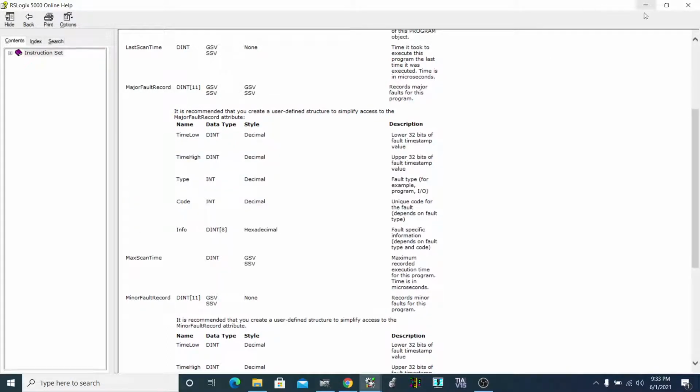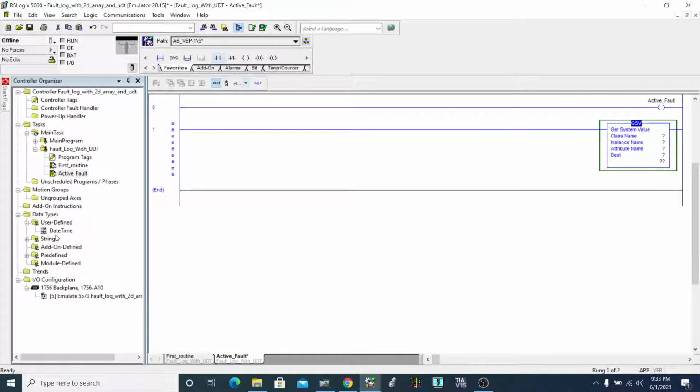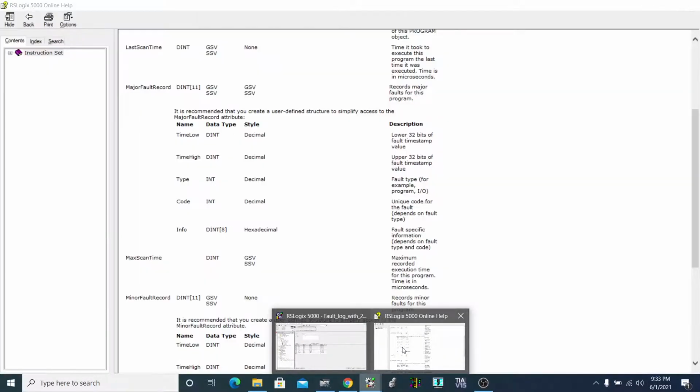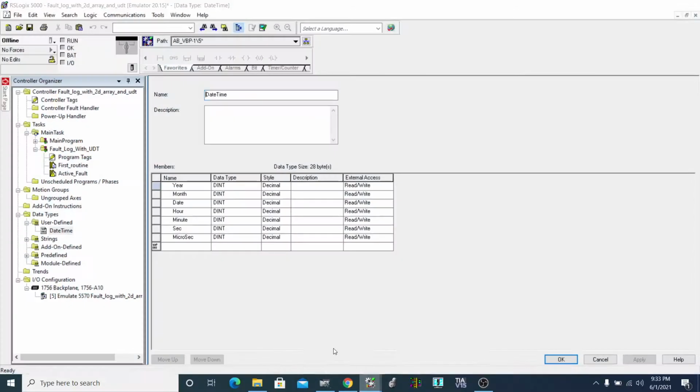So what we're gonna do here now, we already have our user defined tag from my last video. We're gonna just add these values: time low, time high, type, code, and info here. First gonna be time low, it's the DINT. Then we're gonna add time high, it's gonna be DINT again.